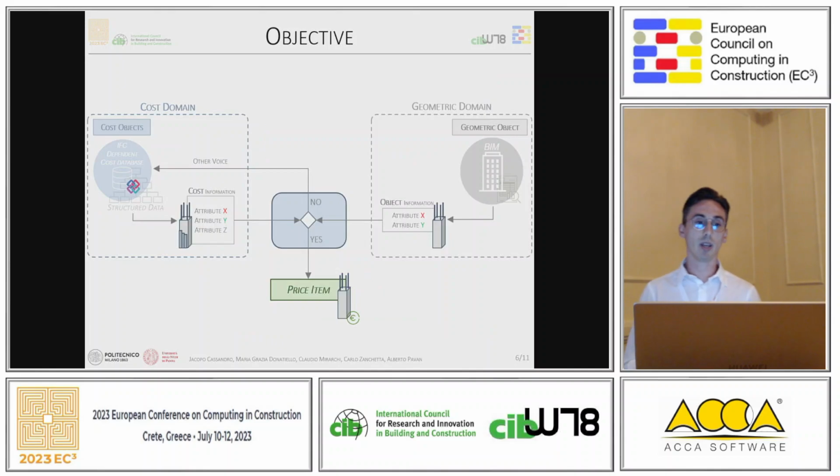The research aims to identify a cost ontology and the standardized supporting procedure to verify that the costs are in line with the model objects. For this, it is necessary to relate the digital model to the cost element described through the structure class in the IFC, and correctly return the analysis and the processes of economic evaluation. It is necessary to have an architecture of cost items, configured as more complex systems than a simple attribute associated with the geometric object.